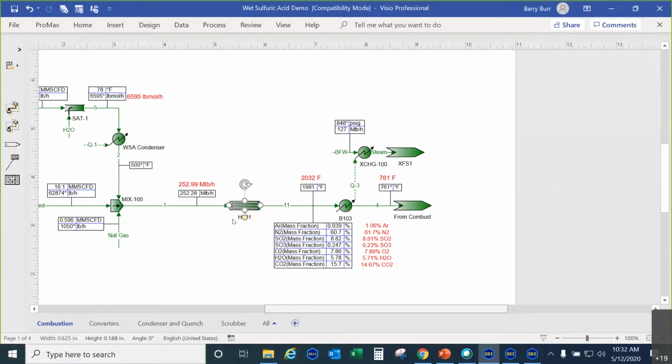But as you're starting out the simulation, you might have some low temperatures, and before you get the simulation working properly, you might run into that situation and your reactor will solve through it. But up at these conditions, I could set that back to 1 maximum phase and it would be okay.